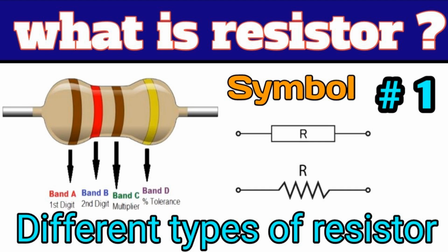Filters are classified based on the frequency range they affect and their configuration. Low-pass filter, LPF. Purpose: allows frequencies below a certain cutoff frequency to pass while attenuating higher frequencies. Application: removing high-frequency noise from a signal or allowing the low-frequency components, such as the DC component in a power supply, to pass. Example: in audio processing, a low-pass filter can be used to remove high-frequency hiss from a recording.